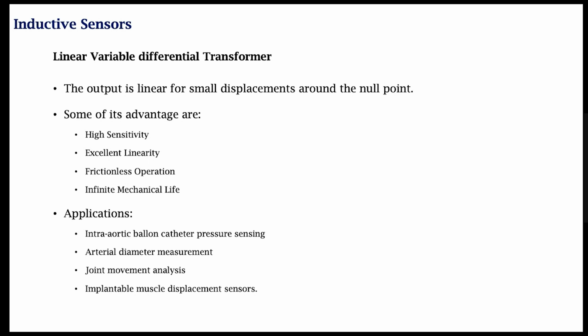The other design consideration is that we can, for example, use a signal conditioning unit within the LVDT system itself, so that we minimize noise at source. So the LVDT housing itself contains a really small analog signal processing system that then maybe converts it into digital form and then transmits digitally, for example. That way you will get output that is digital directly, and you can read this data through, say, Wi-Fi or Bluetooth, for example.